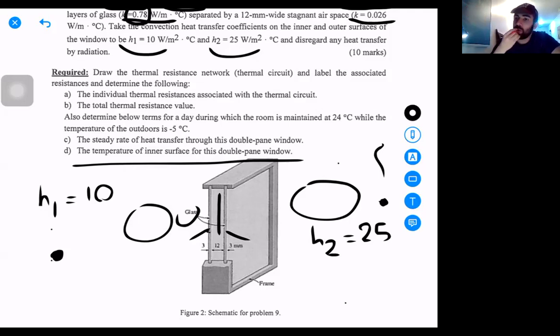So we only need to know the resistivity between the first point and the second point, and multiply it by the heat transfer rate to specify how much temperature difference is embedded between those two points.